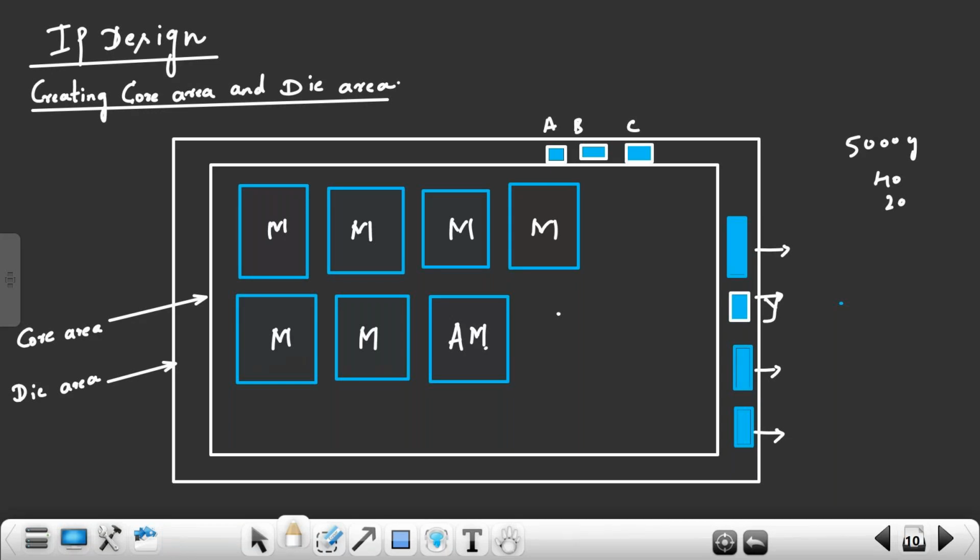No. They can be different library files. The library file need not be one library file. You can have n number of library files: a separate library file for standard cells, separate library files for macros, separate library files for analog macros. Your question is whether we have to use only one library file. No, not like that. You can have n number of library files, different for different cells. I can just tell the tool to look into these library files when you're working. That's it. We have options for that.